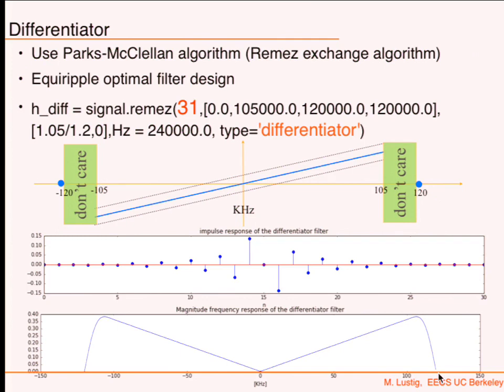When you convolve, in order to compensate for that delay that you have in the filter, you're going to use FFT convolve with a modification which is called same. So you keep the same size after that. When you do that, it shifts your signal such that it's not delayed. Okay? So if you do that over a chunk, after convolution it will be delayed by 16 samples, as it turns out, and then it just moves it back. It does that for you.